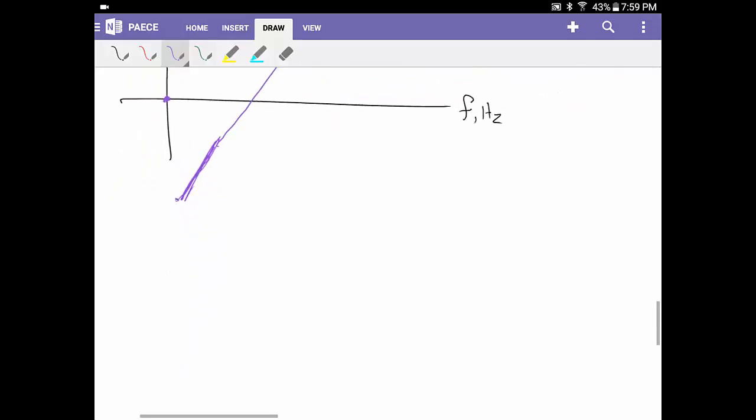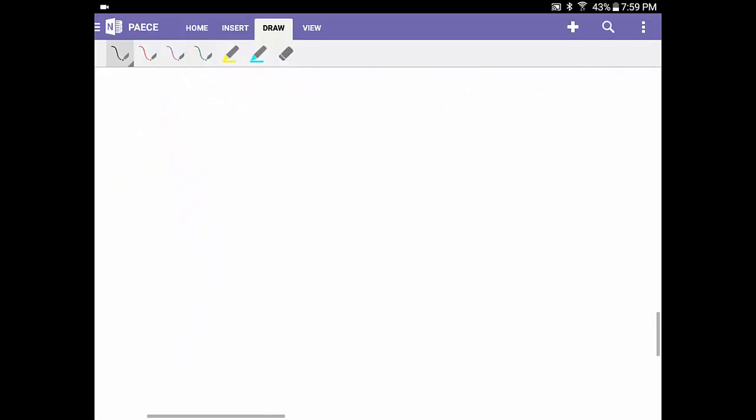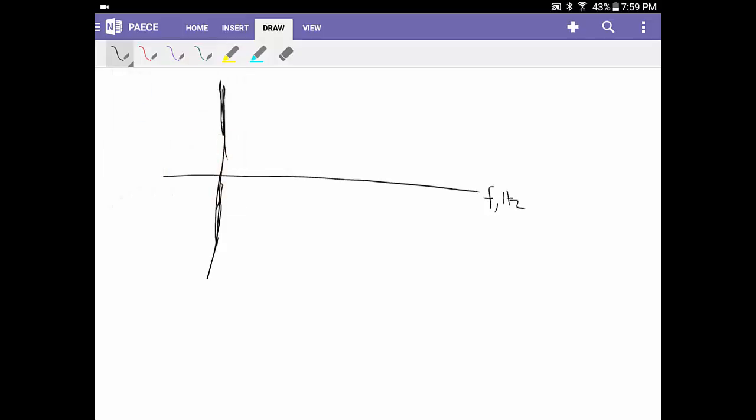The last filter that we need to look at is the bandpass filter. Now, technically, there's 2 ways that you could go about this, and you may be thinking, maybe I can just pass my signal through a high-pass filter and then a low-pass filter. So let me start out by showing you what a bandpass filter's frequency response should roughly look like. We always have these off to infinity type of moments here. So I'm going to end up with F in hertz, magnitude in gain dB.